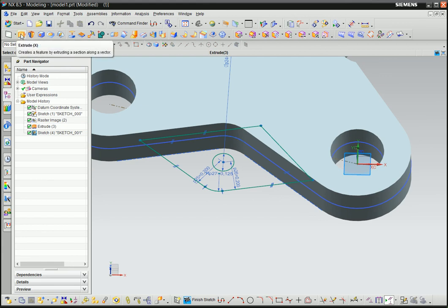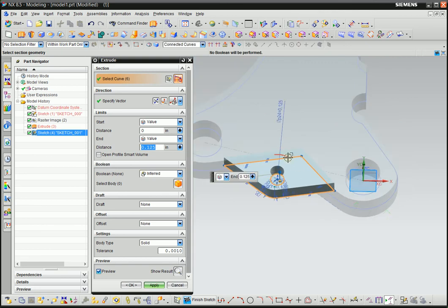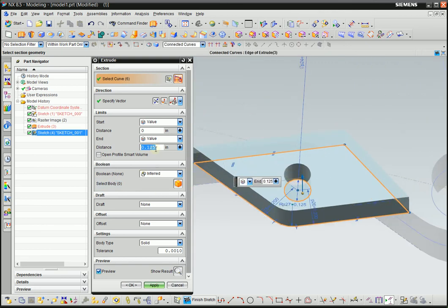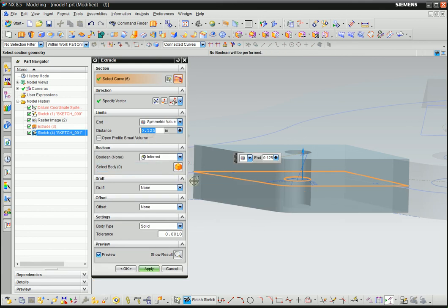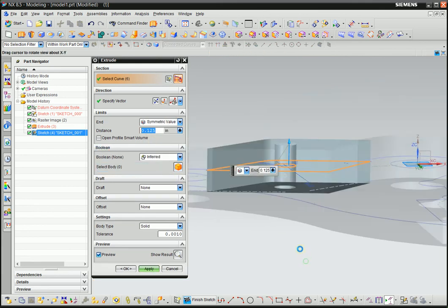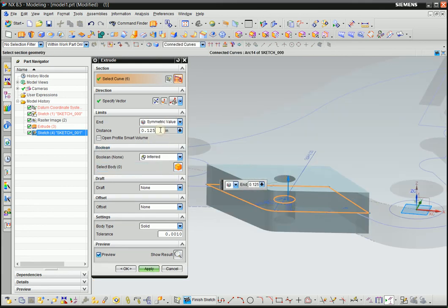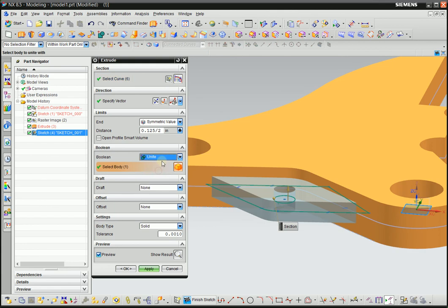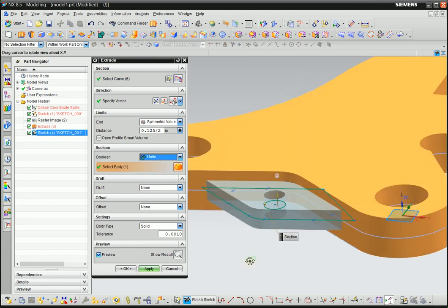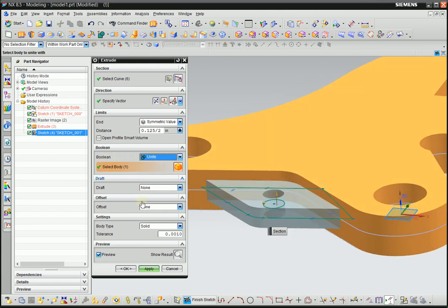We can directly use extrude. You don't have to finish sketch. So this way it's gonna pick the whole sketch, and the thickness is gonna be symmetric again, and I believe that's gonna be half of the thickness, so we can divide by 2. Okay. And you can even do unite here right now. I'm just gonna do it like this. Okay, that's your Boolean operation, unite.